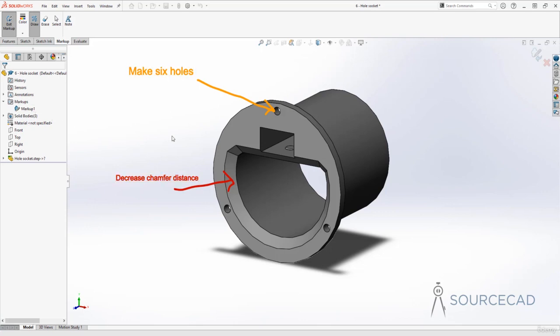So basically I've added 2 separate markups, but SOLIDWORKS will think of it as a single markup because we have added it in just one single view. Now if you want to add another markup in a different view, then you need to first exit out of this markup environment. So I'll just exit out of this, and we have got this markup 1 added here.